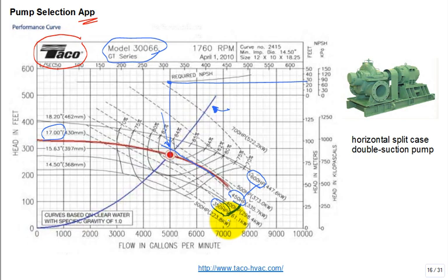You're going to get in trouble as an engineer. People always ask me, why do engineers always over-specify things? Well, this is why. There's really no downside, minimal downside to over-specifying a motor, and yet there's a huge risk if you under-specify one.